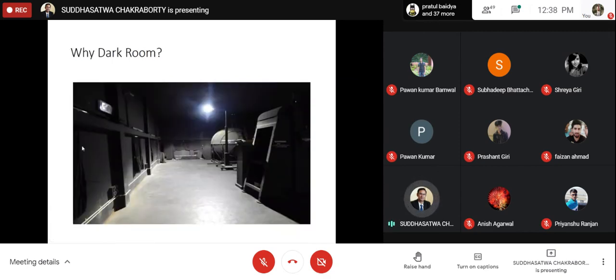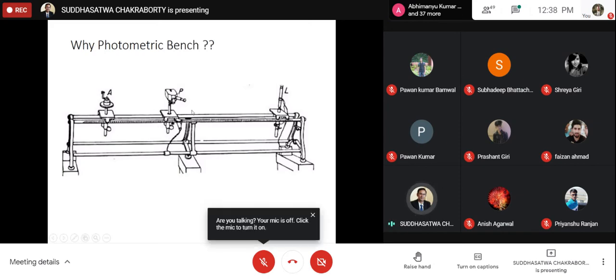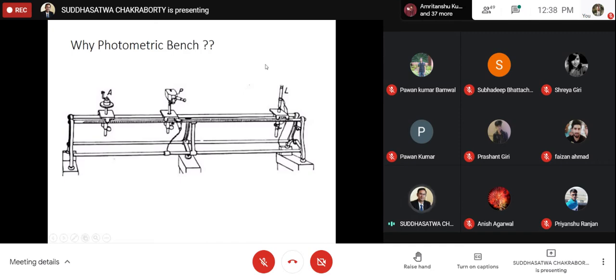Okay, so that is why it is very clear in our dark room, we have a bench photometer, like a photometric bench, over which we are going to put our source somewhere, and just forget about the P portion. P is another one. So A just source, and L we will put the sensor. We are going to measure the illuminance. So that is the idea. So where the distance between A and L will accurately be measured from the photometric bench. Okay. Any doubts so far? Anyone?